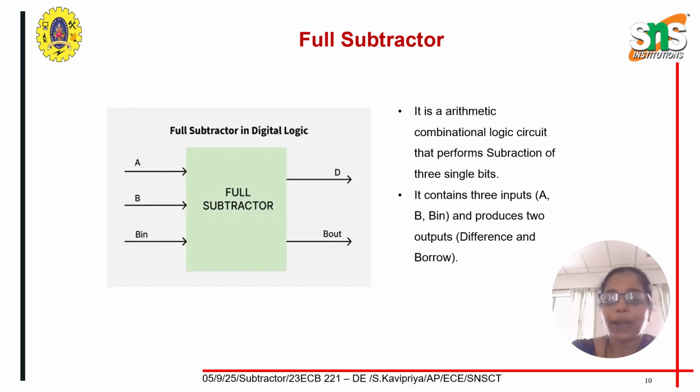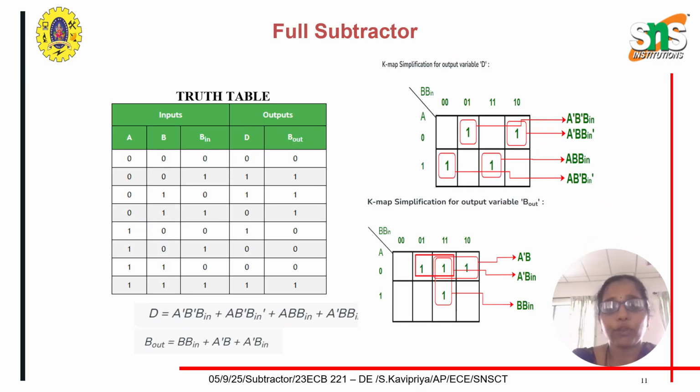And next is a full subtractor. Full subtractor is one which takes 3 bits as an input, which are A, B and B in, and it produces the outputs difference and borrow. And this is a truth table for full subtractor. We have 3 bits as inputs and outputs difference and borrow. Difference will be 1 when input combinations are 001, 010, 100 and 111. And borrow will be 1 when the input combinations are 001, 010, 011 and finally 111.